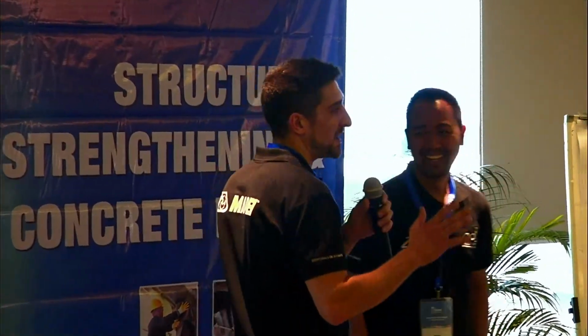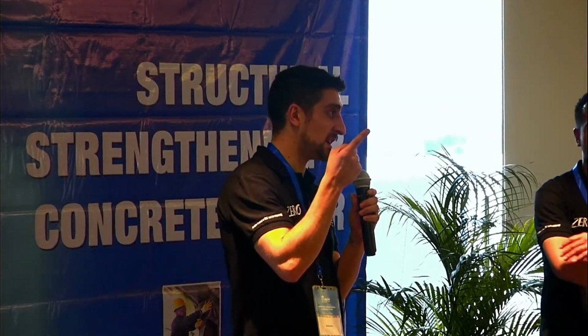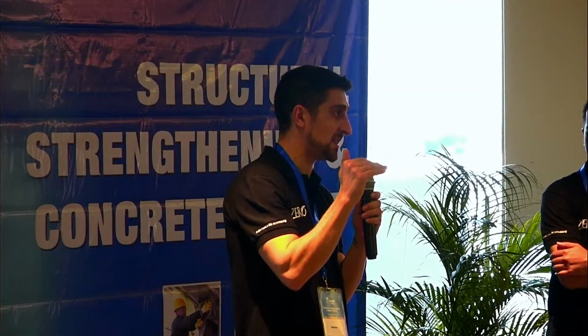Let me say that there isn't anything defined in the ACI 4.0. The only reference that we have worldwide is the European guideline, which advises not to exceed 5 layers. In our experience, if you increase the number of layers, you are also decreasing the capacity of the system.